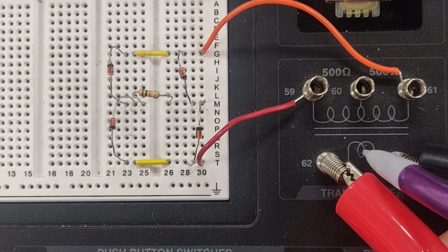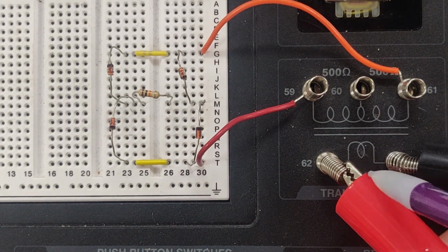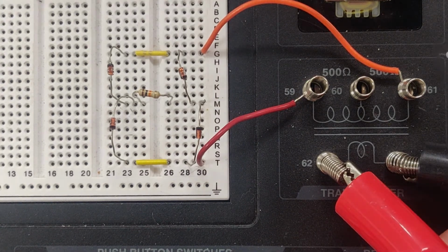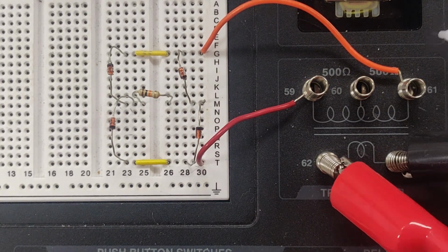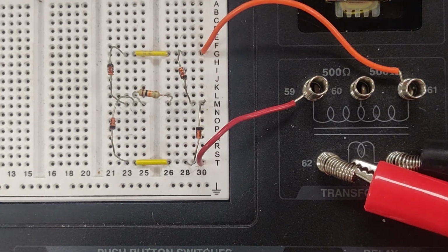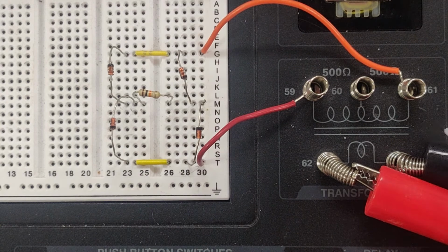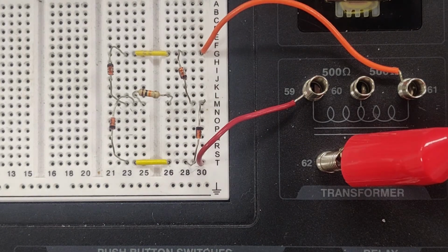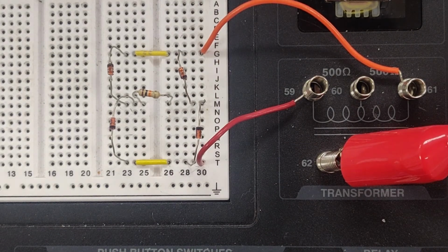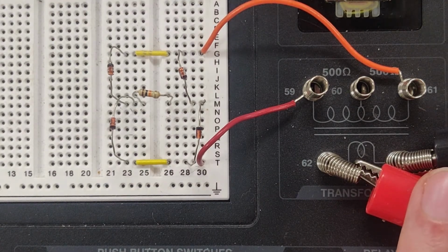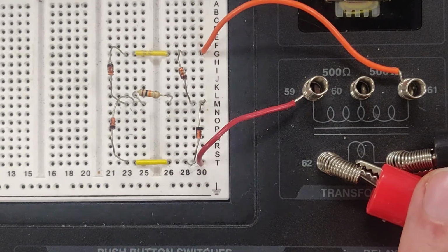And so this is being stepped up. We're going from a smaller amount of coils to a larger amount of coils, so the peak-to-peak voltage of our input signal is being boosted. So we should see a larger peak-to-peak voltage value when we measure the signal up here. I'll show that once we are looking at the oscilloscope. But we don't necessarily want to use the transformer for boosting the peak-to-peak voltage of our signal. We primarily wanted to use it so we can have what's called a floating circuit. We don't really want a ground in the full bridge rectifier, otherwise we won't get the desired effect.